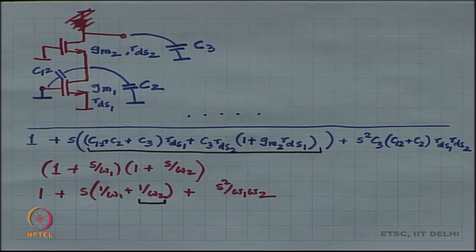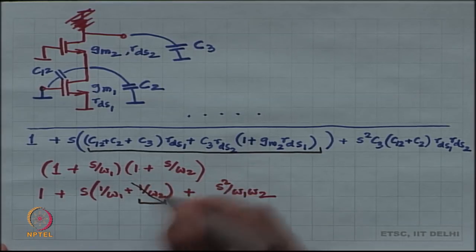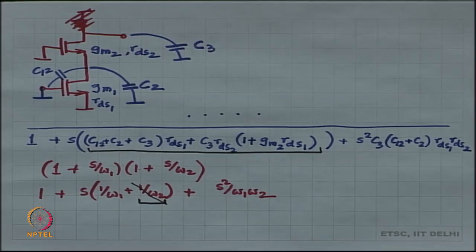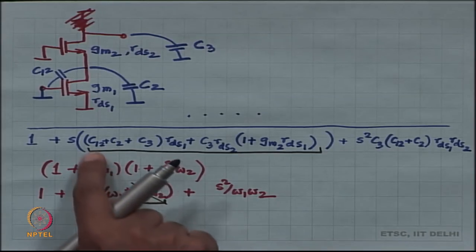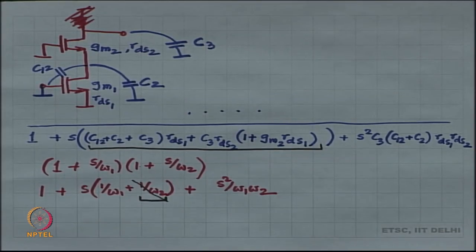So, we know in advance the value of the ratio, right. You can see for yourself that this value of the ratio is some large quantity. If it is not large, then you are probably doing something wrong, right, or you are probably dealing with a phase margin that is not sufficient, correct. So, immediately you can tell that 1 by omega 2 is not really a concern, in which case 1 by omega 1 is nothing but what you have got in coefficient number 2.